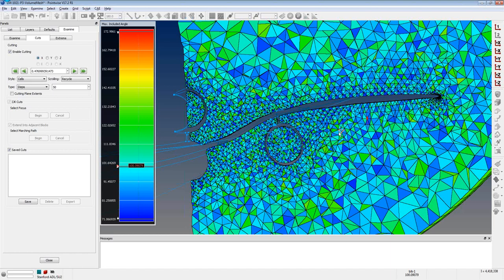It's easy to automate, so we could pretty much script this entire process for creating the volume mesh and that far field geometry. But again, the other thing is if you're satisfied with the surface mesh resolution, the way that you're capturing the geometry, you could easily convert this to a viscous block by bringing it into T-Rex, specifying things like your number of layers, your growth rate, some quality constraints, your initial delta S, given a target Y plus value, etc. So then you can just reinitialize the block, and you've got a viscous block out of it. So you really do have a few options by going this route.